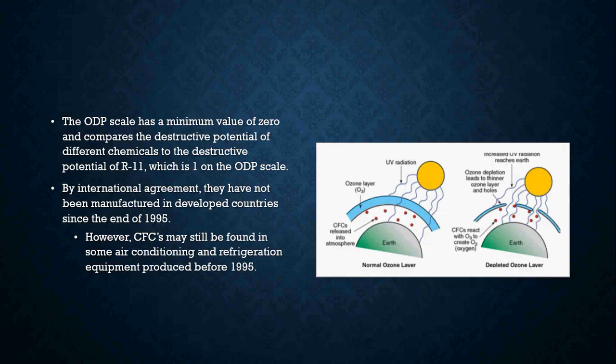But bottom line is, regardless of the type of refrigerant that you're dealing with, you still have to recover it, reclaim it, recycle it properly. EPA does not want you venting refrigerant at all. We have to take it out of our system and store it in an external cylinder and do it safely and, obviously, with the correct techniques.